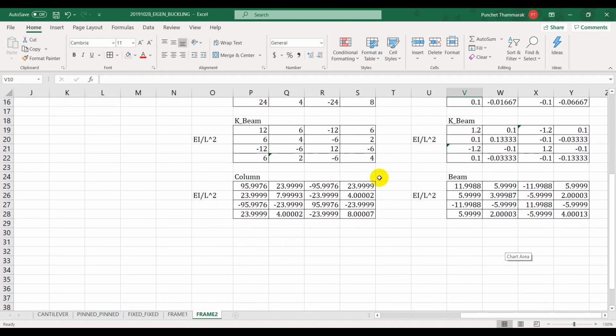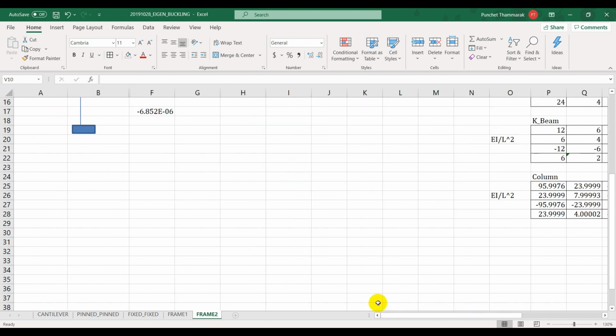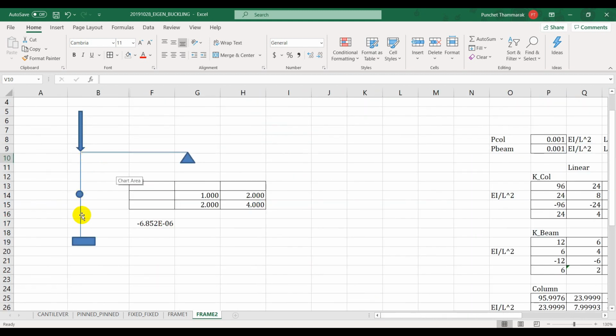The further from the point where you have the maximum moment, the less accurate the solution you will get. So for example, if you have the upper column length equal to 0.8 and then the node is coming down here, then this is quite a silly option, right? Because you don't think that it will deform much at this point.